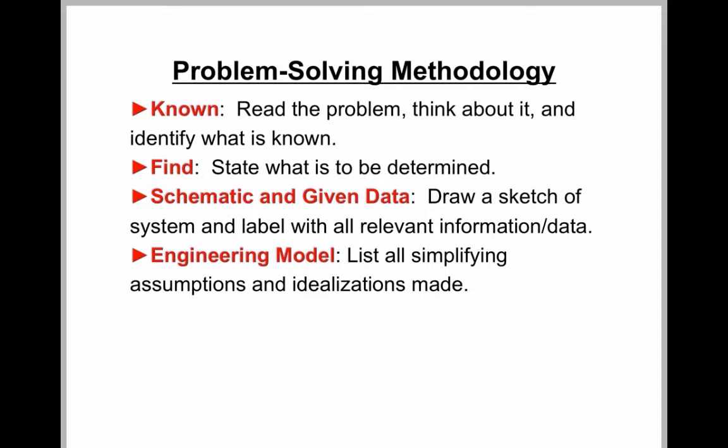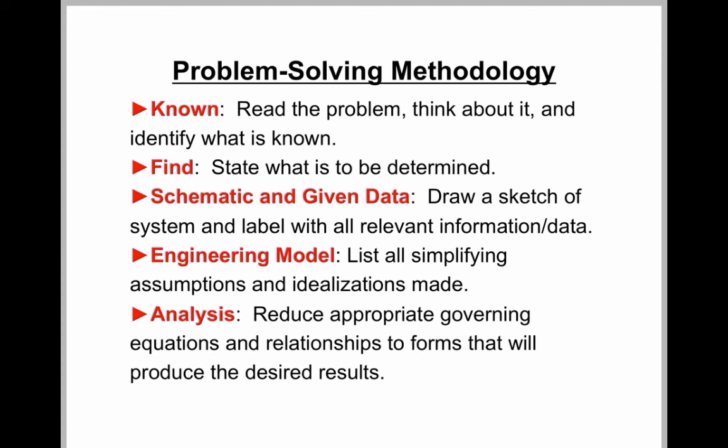Are you at steady state? Are you assuming that the changes in kinetic energy, potential energy, internal energy are or are not significant? Once you have that done, then you can begin to go ahead and analyze or solve the problem.